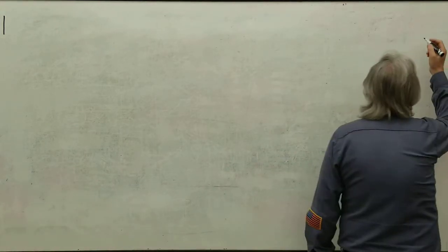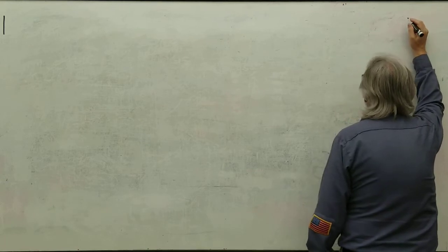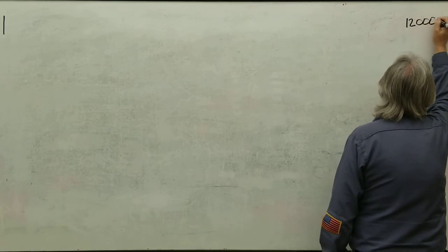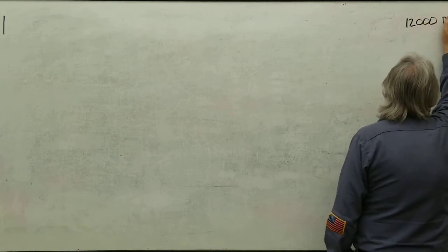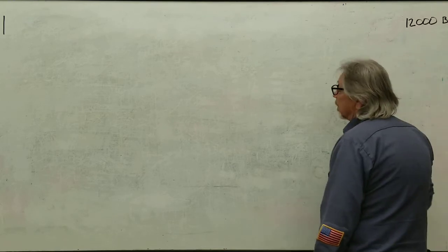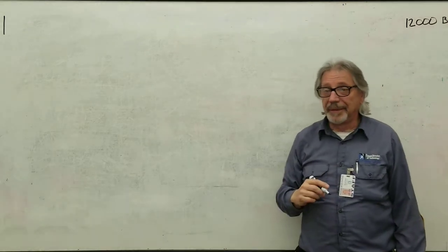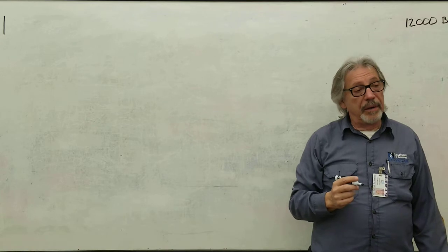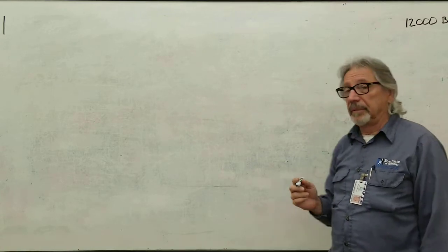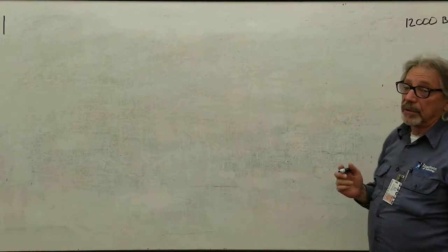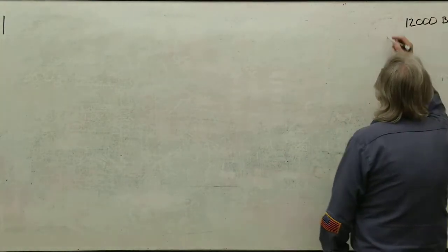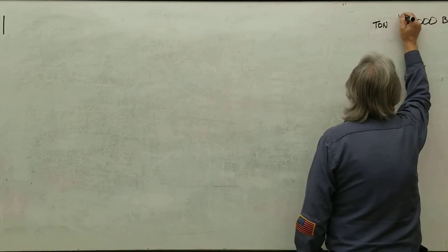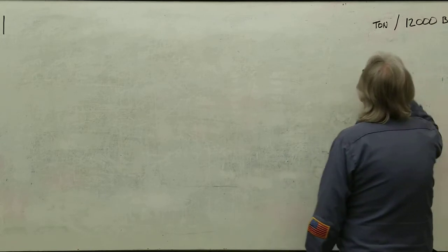288,000. Right? To how much? 12,000. Oh, that's refrigeration. A ton of air conditioning is 12,000. It would be 288,000 if it was BTUs per day, 24 hours. Yeah, that's the other one. Which is 12,000 BTUs per ton, right? So that's the ton. Yeah, 12,000 BTUs per ton.